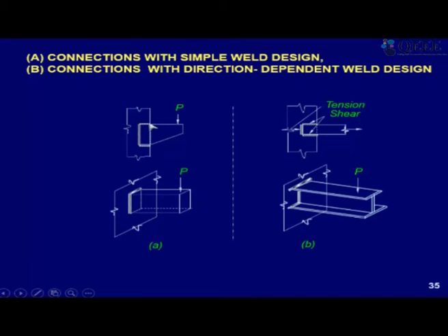For this, you can either assume that L into 0.7 as the area and take moment of that area and locate the CG, or alternatively 0.7 is common throughout, so you can just take L into its moment, right? So then finally you can adjust with the 0.7 S that you have. Okay, so length of this into its moment about, let's say, the bottom line I take, then the vertical length into its moment about the bottom line, and this will have 0 moment, divided by the total area, that is the total length in this case.